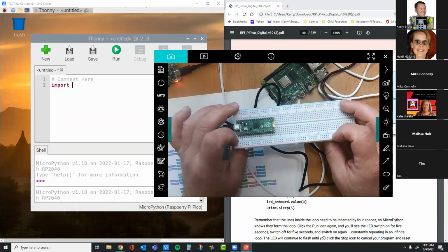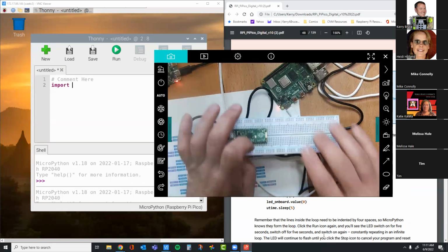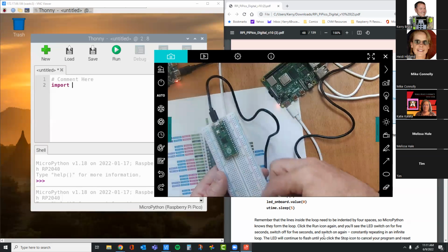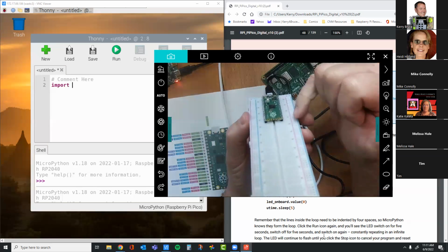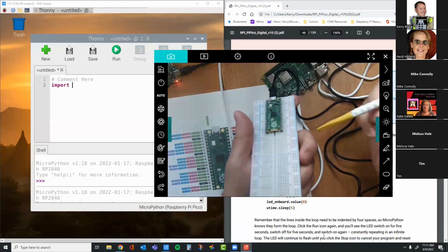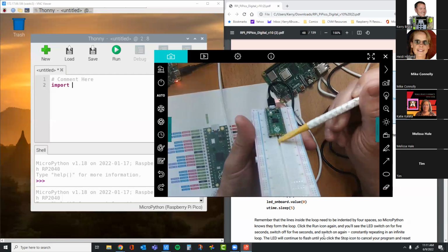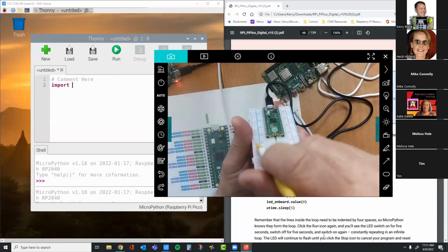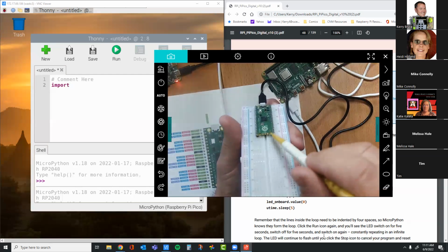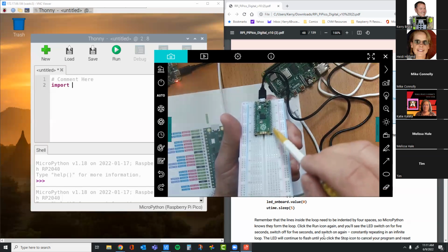Oh, okay. Because if they're not pushed into the board, actually, let me show you. Hold on. And it doesn't matter where that's connected on the breadboard, right? No, it could be anywhere. You do want to bridge the gap there. So we want this set of pins on one side of the gap and this set of pins on the other side. Because if they're on the same side, which you shouldn't be able to plug them in on, because they're wide enough, they create a different circuit.